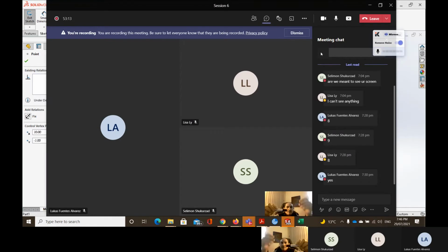I brought the cutting tool to here first, then I went in touch with it to a certain depth, then I go to the center. I just removed a layer. Whatever it is going to be, this will be decided by the Z value I'm going to send. For example, if I send it to Z equal to -1, then I'm going to remove 1 millimeter from the face, then continue doing the work.